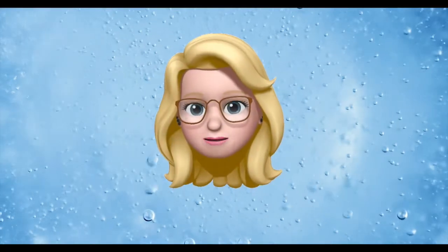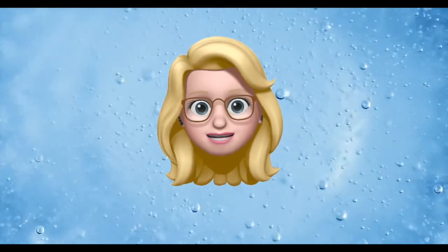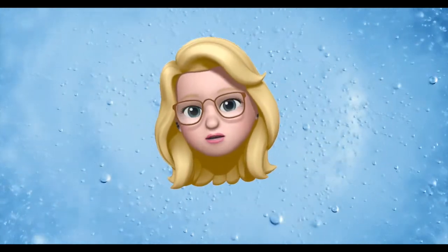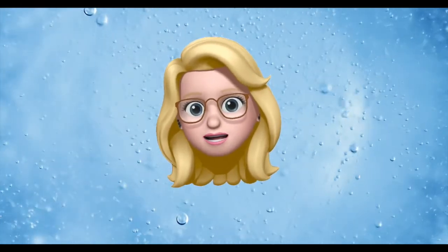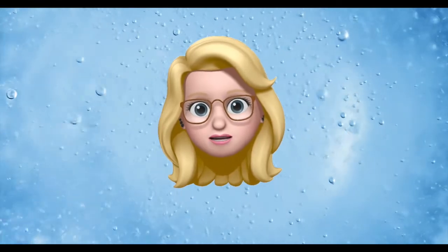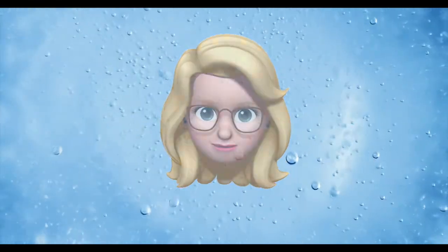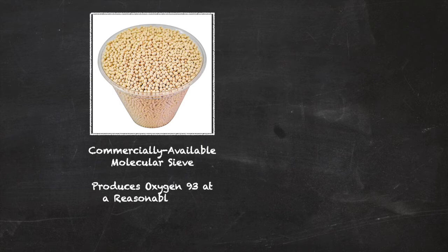To be clear, it is possible to produce oxygen at 95% or higher using a single-stage, single-bed vacuum swing adsorption concentrator. However, they are not commercially available due to the high cost of zeolite, which is a necessary piece of separating nitrogen from oxygen. Single-stage concentrators use commercially available molecular sieves, which is part of the reason why most concentrators are limited to output no purer than oxygen 93.